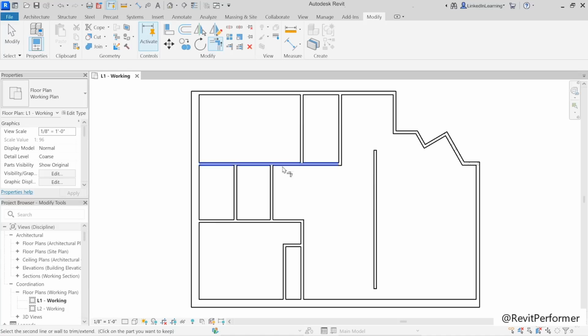I'm going to select the horizontal wall right about there, and then this vertical wall right here. And what you'll see is that it actually trims off the part of the wall past where I selected it. Now, looking at that, that's probably not what I wanted. So let me reverse that by simply selecting 2 different walls this time to reclose up that cavity. So the way that this command works is you simply touch 2 objects, and based on the way that you select them and their current configuration, it will either trim their lengths down or it will extend their lengths out. So here's an example of when it would do extend.